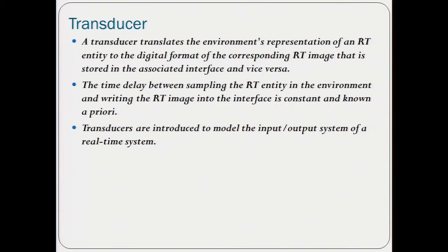It has to say, this is really something that I need to send out, right? So it is then pushing the data onto the system. The pull is when you have this sampling mechanism, in which the computer says, okay, what are you reading? What is your last reading? And then the sensor communicates the last reading. So the push model is in general asynchronous, and the pull model is the synchronous operation, right?